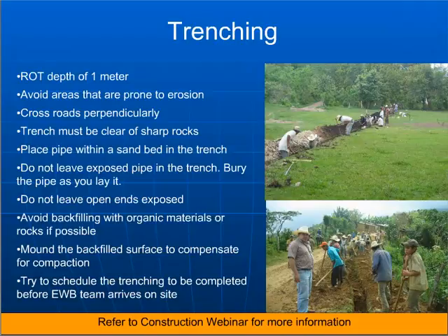There are a lot of issues to consider and a lot of guidelines to be aware of. I think the biggest factor that you'll want to develop a feel for very quickly in the project process is figuring out how easy it is to actually dig a trench in this area. If you're proposing a project that's going to have a 5-kilometer pipeline, but it's all rocky ground and nobody can dig through it, then that's going to pose some serious problems.